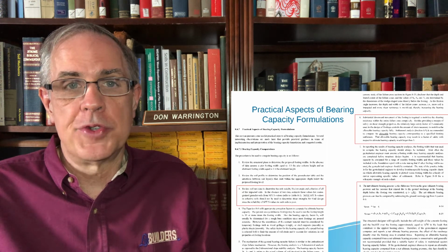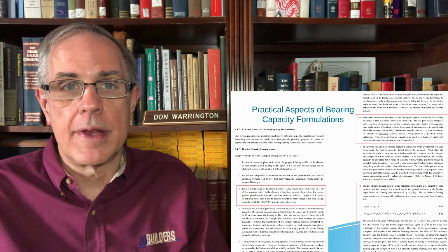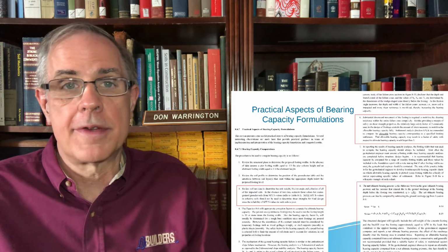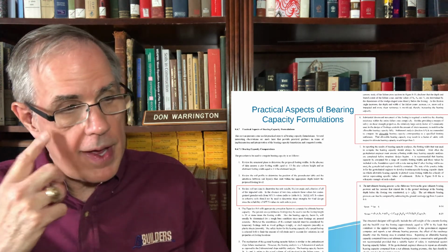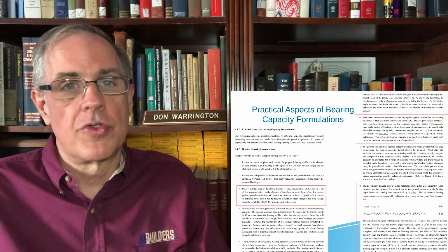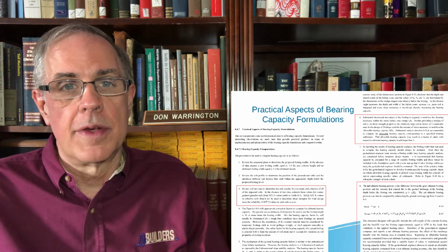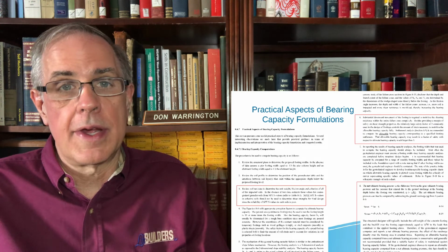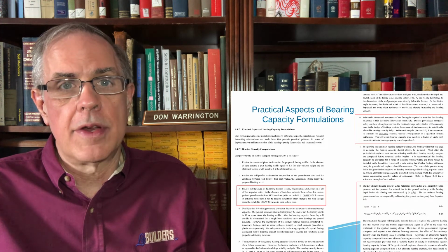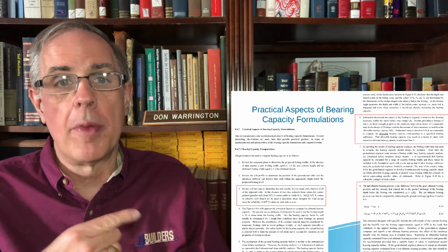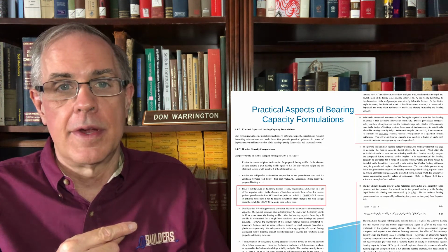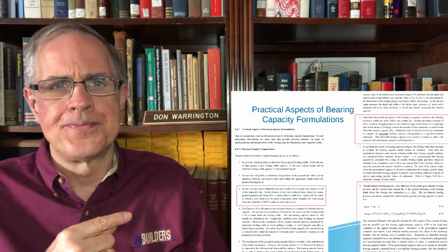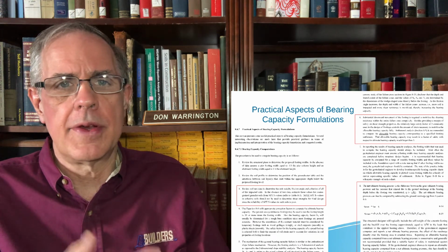Soils move from the time you start loading them, and the elastic purely plastic model is better at predicting that. You need to combine any soil analysis of bearing capacity with analysis of settlement, not just to fully mobilize the soil. I want to talk about mobilizing soil resistance a little more in deep foundations, but you need to keep that in mind.